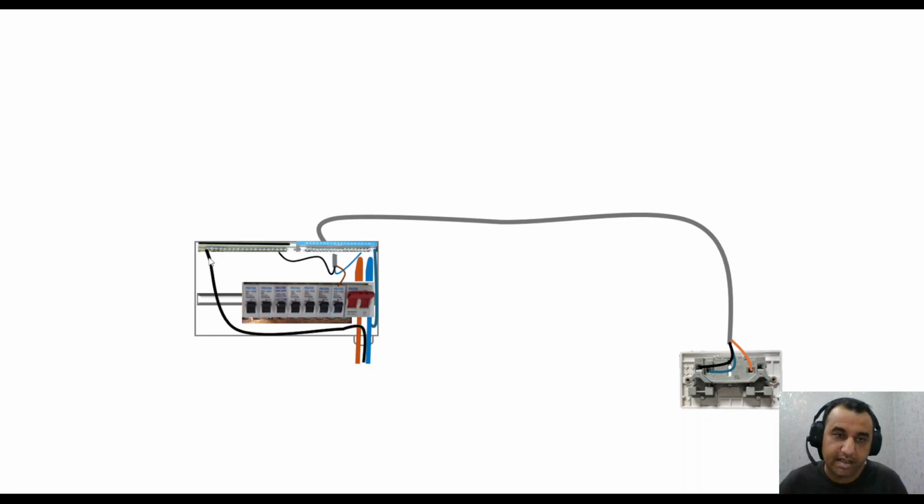So this earthing terminal is linked to the main earth distributor earthing arrangement. This cable is the main earth that's connected to this earthing terminal. So far we've got 3 cables here: the meter tails, one of which is the line cable, that's going to be your main line cable, then the neutral cable, and then the earth cable there.